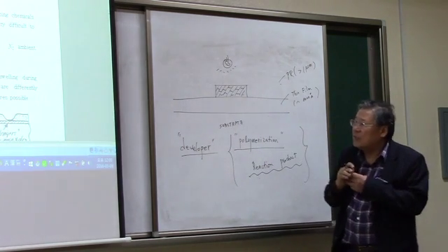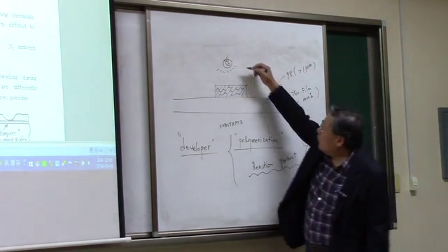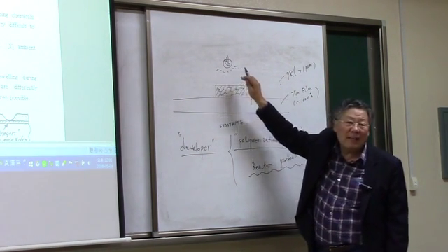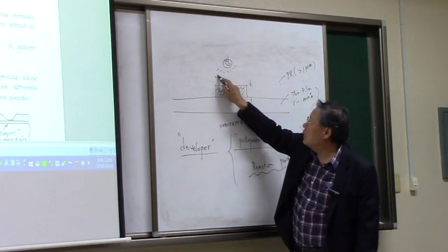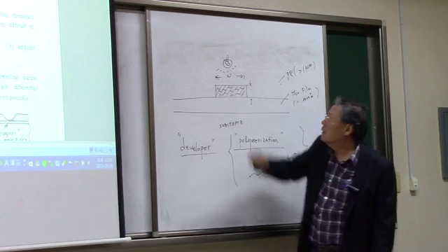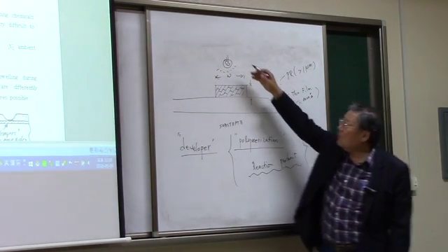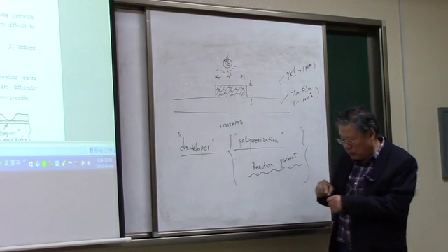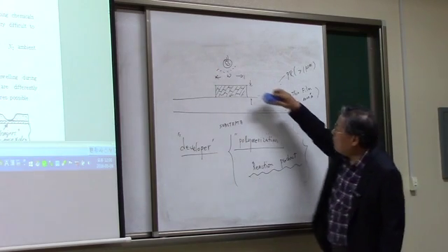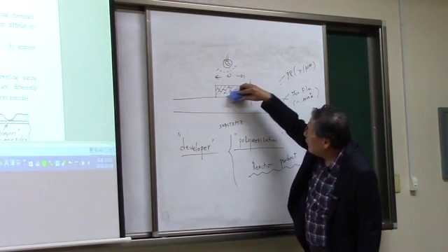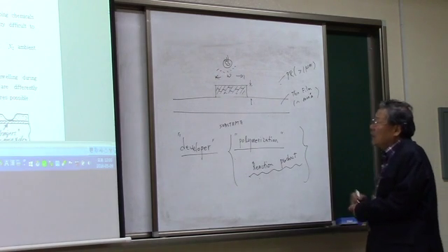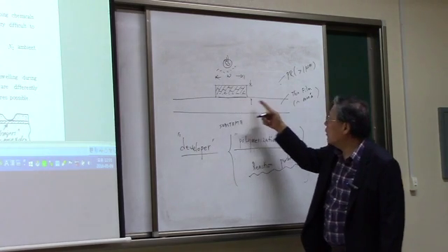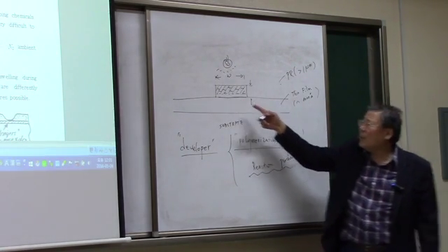And typically two things can happen. The one thing is when you shine the light, depending on the thickness or the light intensity, the light may not be enough to penetrate all the way through here. So this polymerization can happen to the top surface, but not the entire thickness, so that a certain layer very close to the thin film may not be polymerized.